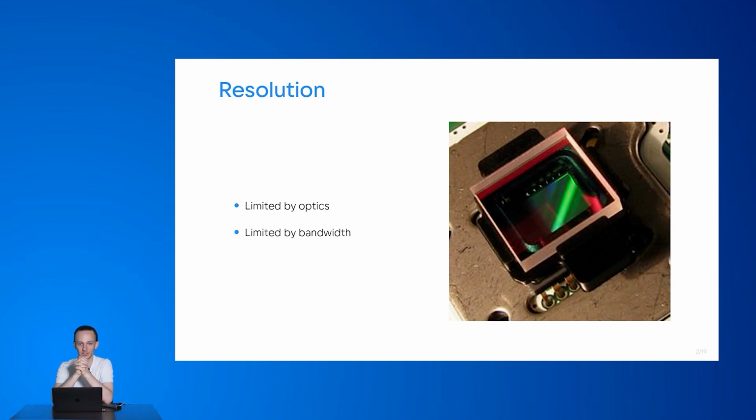Let's talk about resolution in slightly more detail. Obviously, we want the resolution to be as big as possible, but there are certain limitations to this parameter of the camera. The first of them is the finite wavelength of the light in the visible part of the spectrum. That's maybe too silly and obvious, but let's just state it clearly. The wavelengths of the photons are really small. The green light is, let's say, 500 nanometers. That is half of a micron, and a micron is 1/1000th of a millimeter. Those things are pretty tiny, but still they are finite.